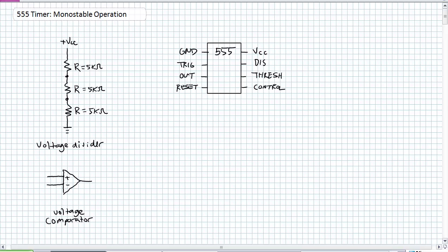Okay, internally, what does a 555 have in it? Most famously, a voltage divider with three 5k ohm resistors. Do you get it? 555 timer. So we've got a supply voltage at the top of those, and then it's hooked to a ground. So there are 3 identical resistors, regardless of the resistor value. I know they're 5 kilo ohms, and regardless of the VCC, I certainly hope you'd be capable of figuring out the voltage divider there. That is going to be 1/3 of VCC. That is going to be 2/3 of VCC.